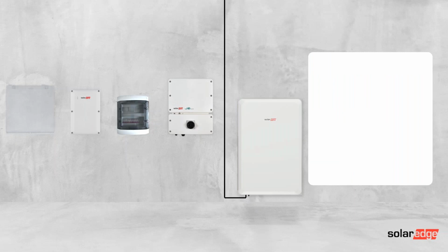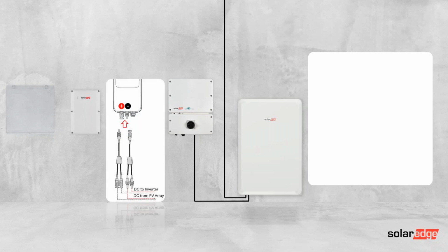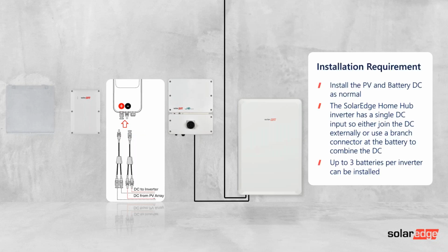So wiring it, obviously the DC, just like I explained with the 3-phase, the ideal is you bring the DC to the battery, use the branch connectors, and then go to the single DC input into the inverter. Now, if you were to have multiple batteries, you can just do the same. You can just use the branch connectors to link them all together. So super simple.